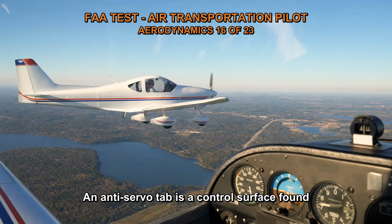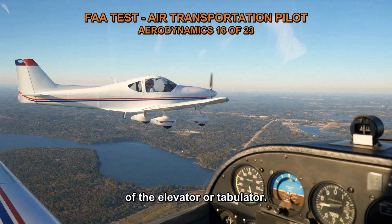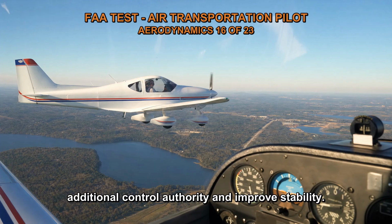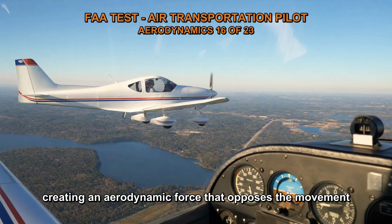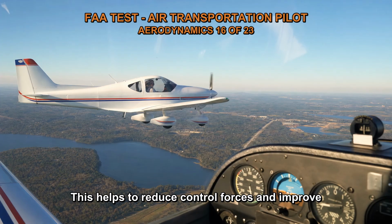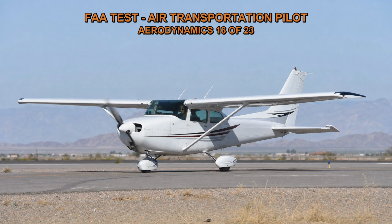An anti-servo tab is a control surface found on some aircraft, usually on the trailing edge of the elevator or stabilator. It moves in the same direction as the primary control surface, elevator, or stabilator to provide additional control authority and improve stability. When the pilot deflects the primary control surface, the anti-servo tab moves in the same direction, creating an aerodynamic force that opposes the movement of the control surface. This helps to reduce control forces and improve the overall handling characteristics of the aircraft.